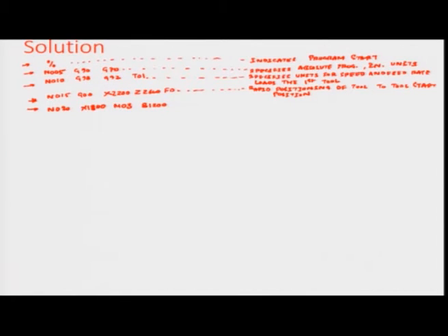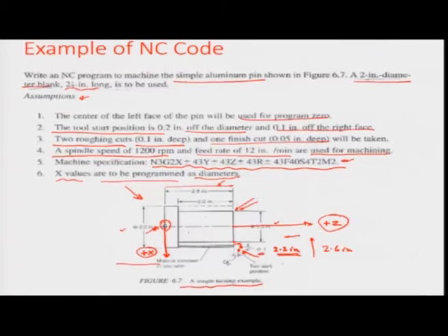Okay. And in this particular condition, once the positioning of the tool goes to 1800, what it means is that from this position, when it is still off the face of the workpiece, it is going in this vertical direction and standing here as the spindle has started moving and the workpiece has started rotating.